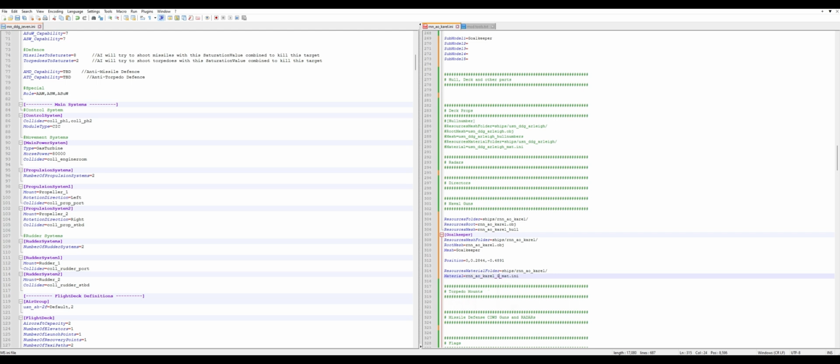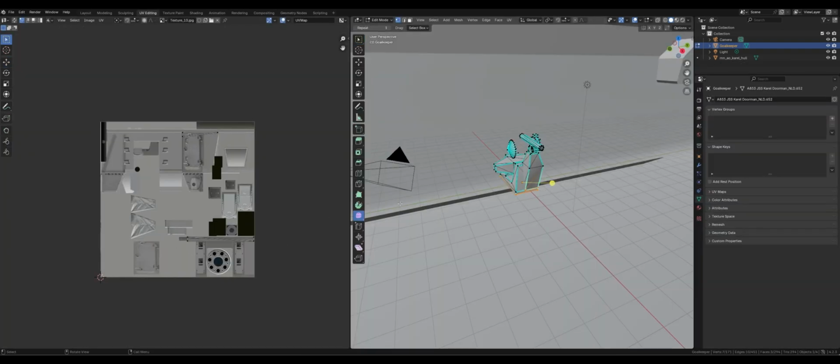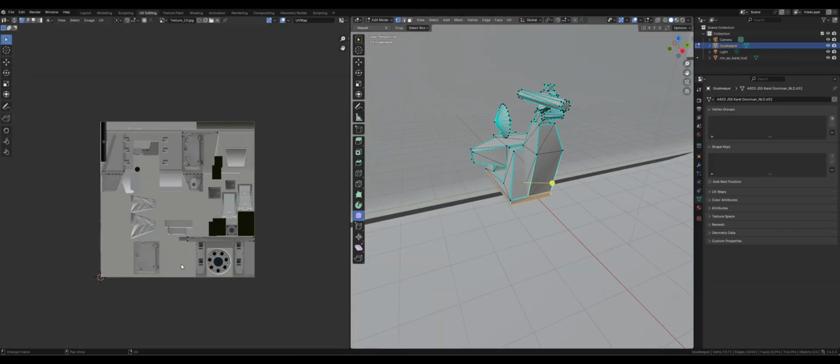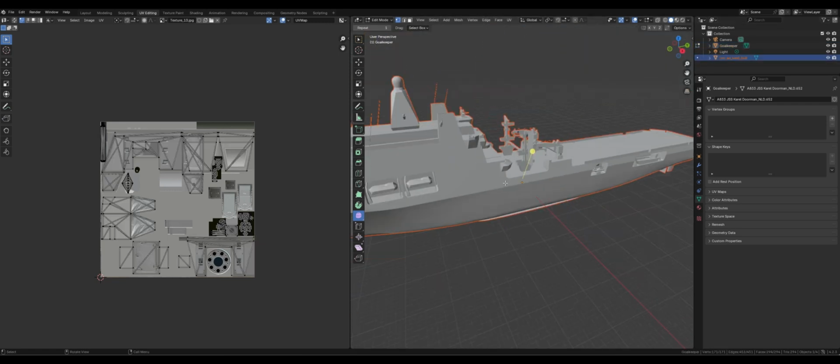And then I'm gonna make an extra separation, because for the goalkeeper you can make its own textures. It's easier than doing it in a complete UV map, because with the UV mapping in Blender, you don't have that much space for everything. As you can see, I have the goalkeeper here as one mesh, and then I have the Karel Doorman hull.